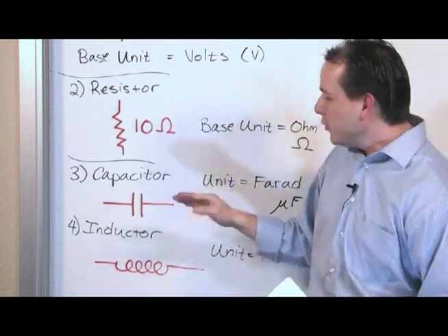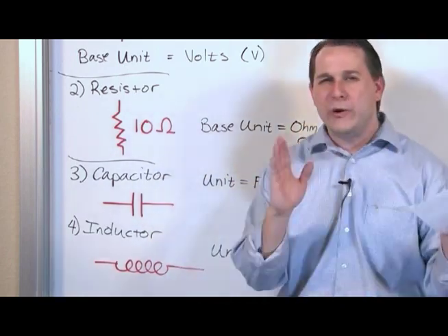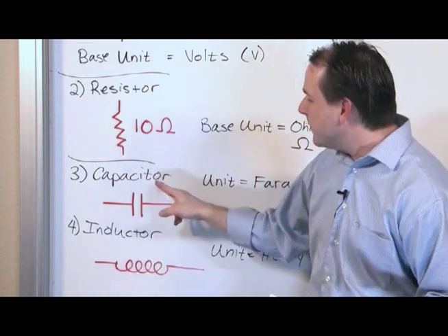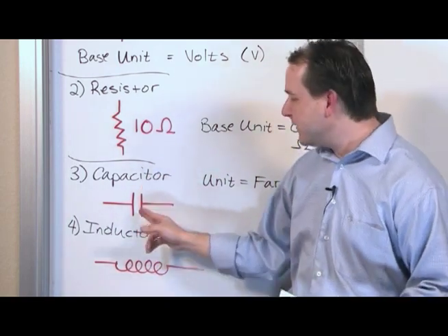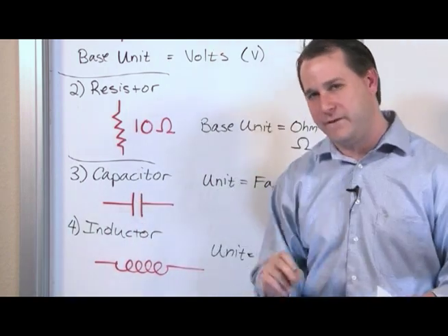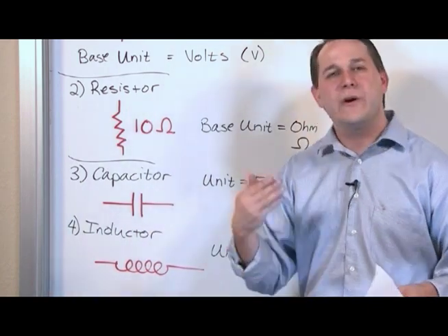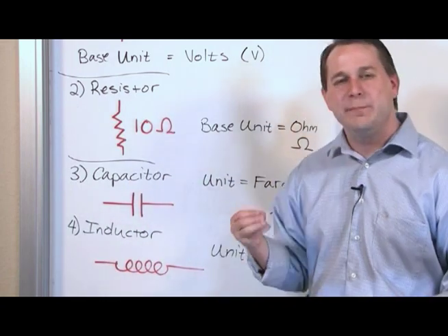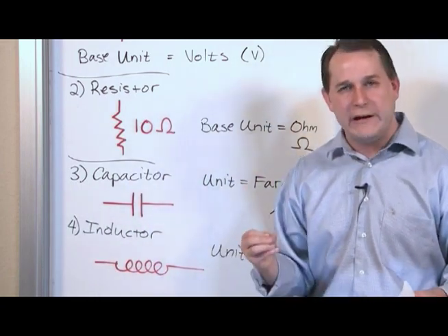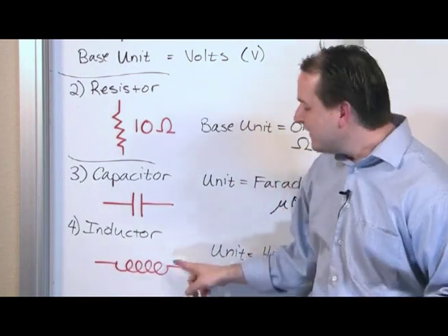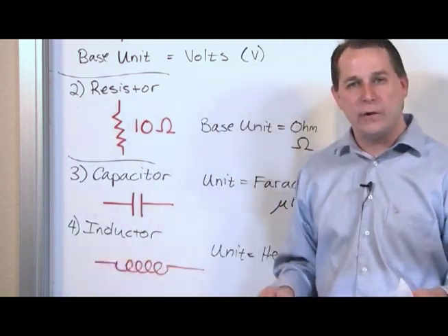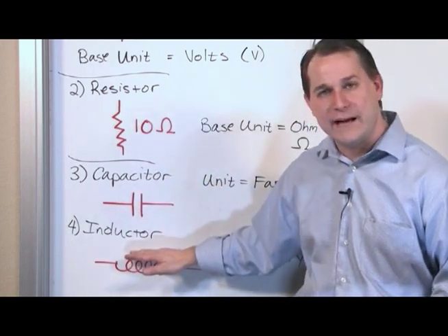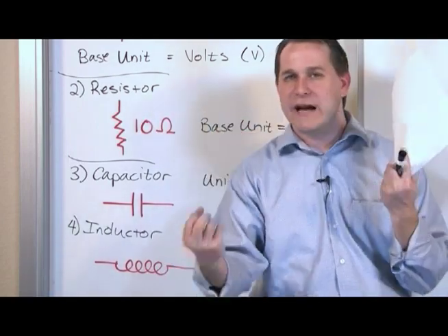Step back with me for a second and realize that a capacitor and an inductor are really nice mirror images of one another when you think about it. I told you a capacitor is constructed to basically concentrate the electric field inside the plates to store energy in the form of an electric field between the plates. The inductor is specifically constructed to store energy, but not in an electric field, as a magnetic field that's inside the coil. This guy stores energy as an electric field. This guy stores energy as a magnetic field. Electricity and magnetism kind of go hand in hand.